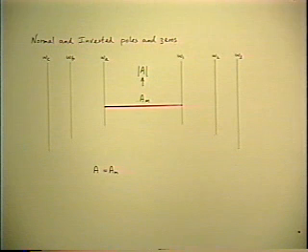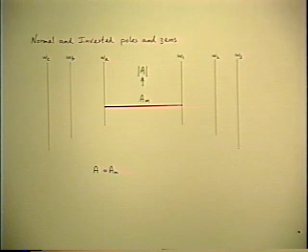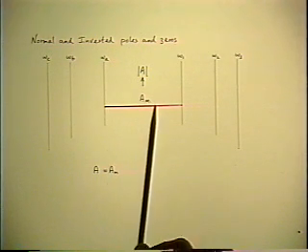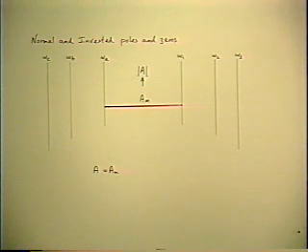There's a flat gain. Call it a mid-band gain again, just for simplicity. What I'm going to be emphasizing now is the relationship between the asymptote sketches and the factored pole zero forms. Because probably what you're used to doing is doing the algebra, getting the equation, finding the poles and zeros, and then drawing the sketch. What I want to emphasize now is the reverse process.